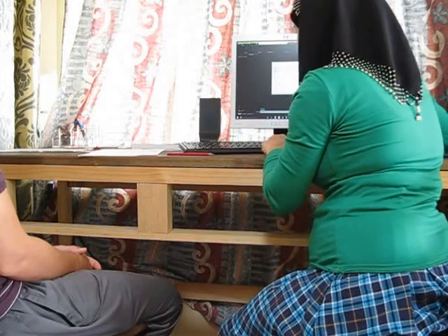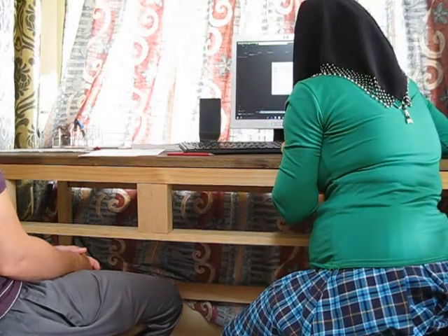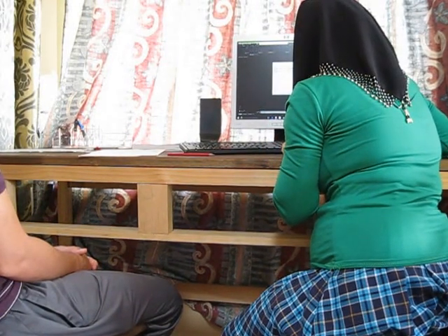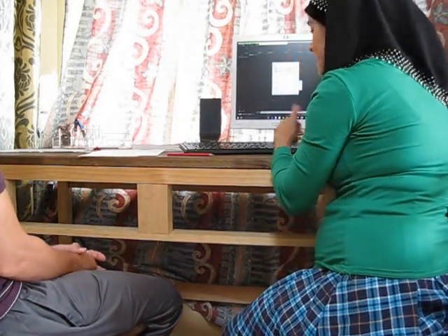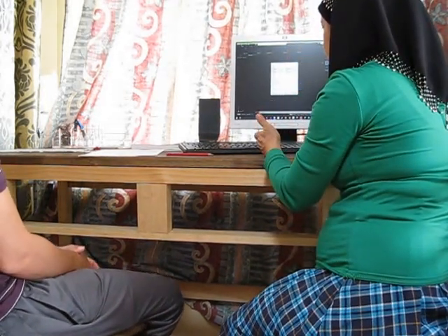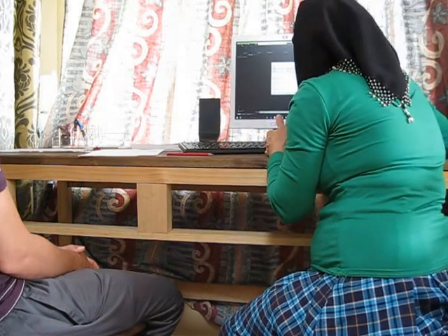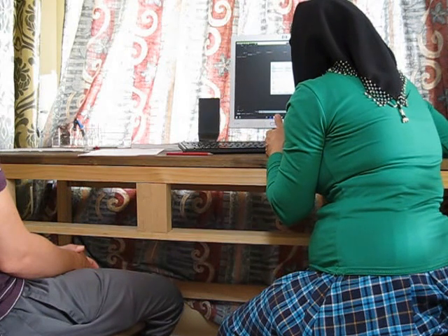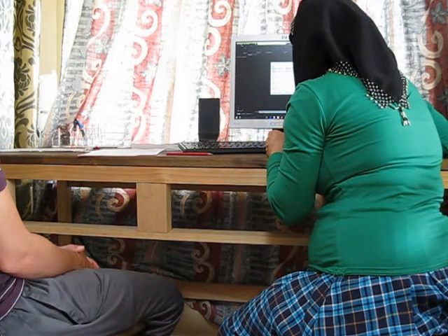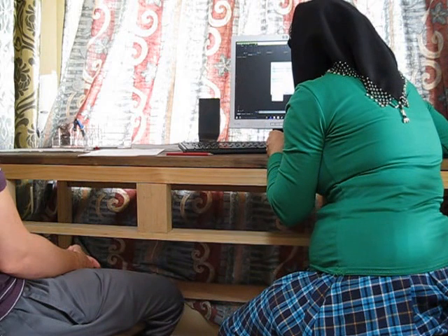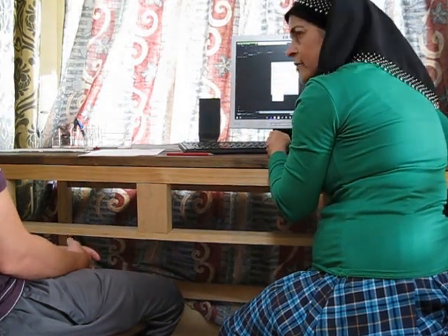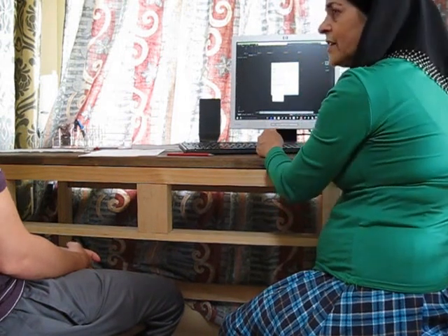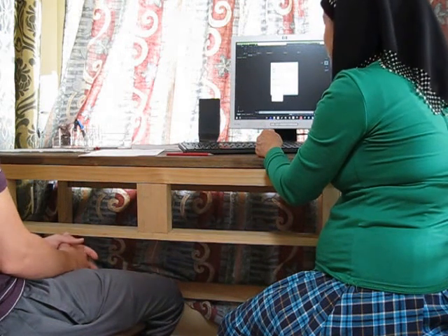This dialog box opens, and in this one it asks whether we want inches. It is set up by default that all the measurements be units to a scale. Inserted content is inches. We do not work with inches here, so we have to change it to millimeters. We can also change it to centimeters. In the building industry, millimeters are not very useful because the scales are very big.